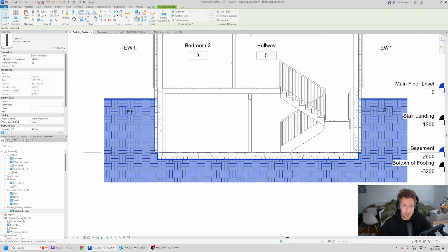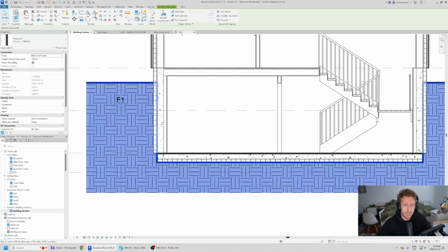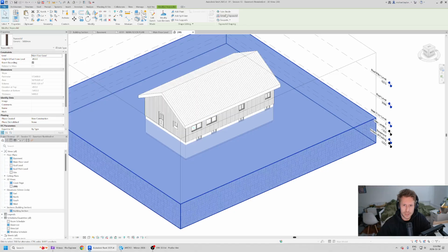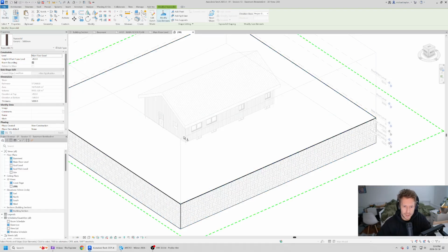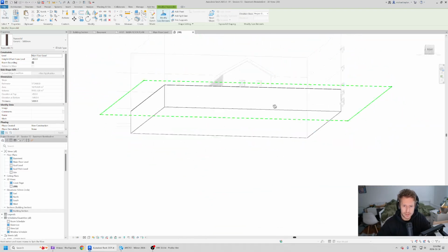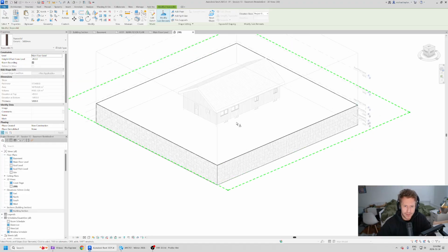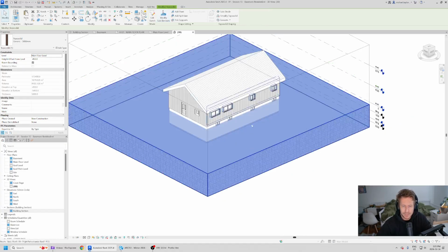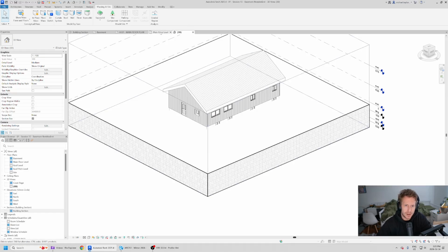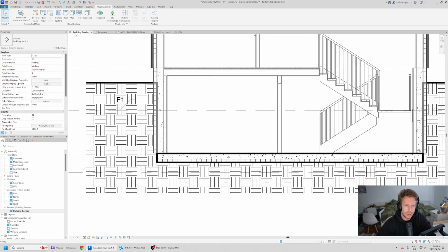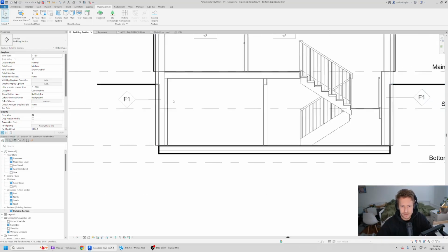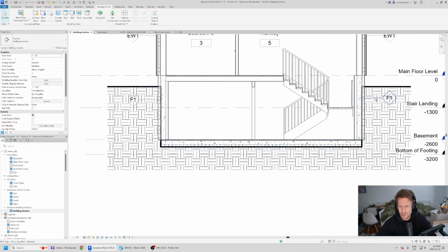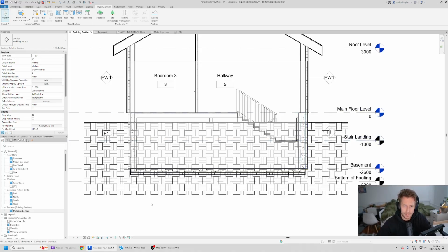So I thought maybe if I went back to 3D and looked at the Modify Sub-elements tool here, that I would have something to touch. But in fact, it's useless. So that excavate tool isn't the most helpful thing. So I'm just going to reset the shape, make it flat, have it cut through our basement, and we're going to use a slightly different tool. It didn't even work, so I'm going to unexcavate that. So I'm going to just undo. Okay, we're all the way back.